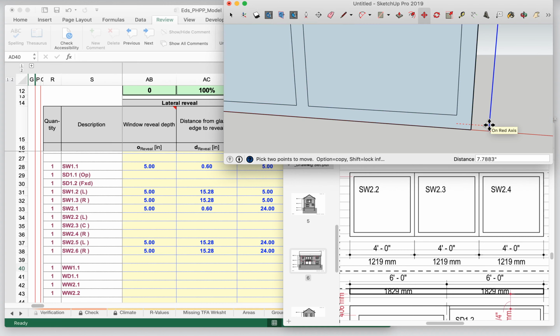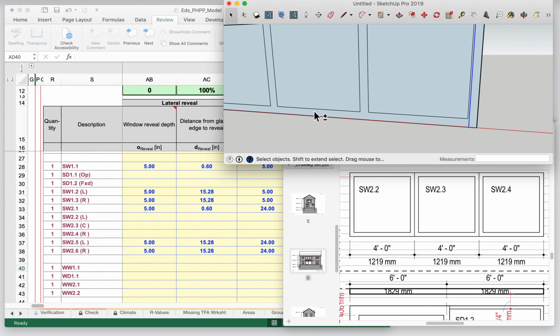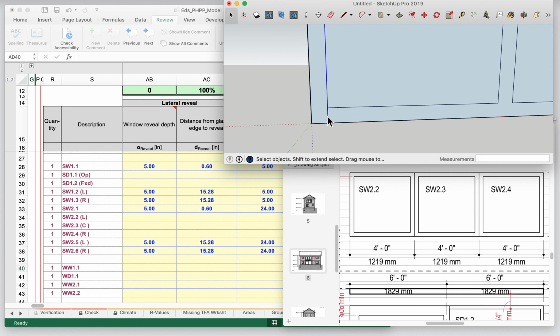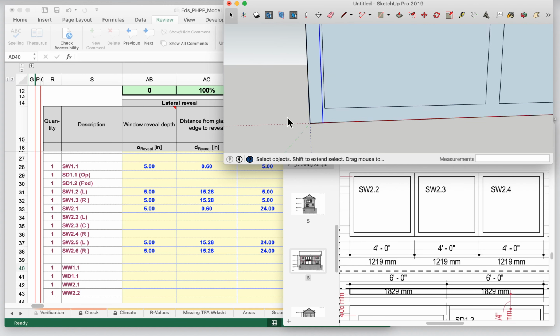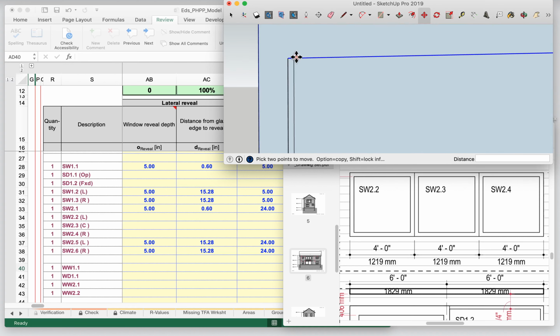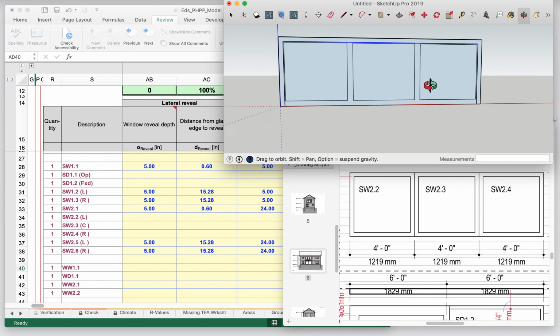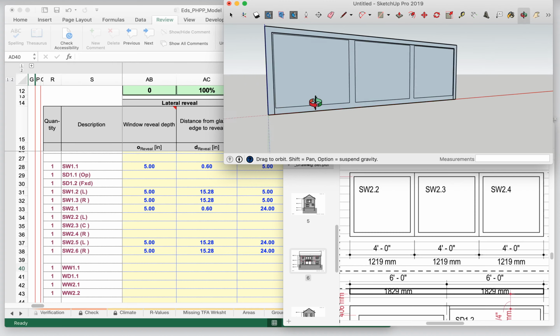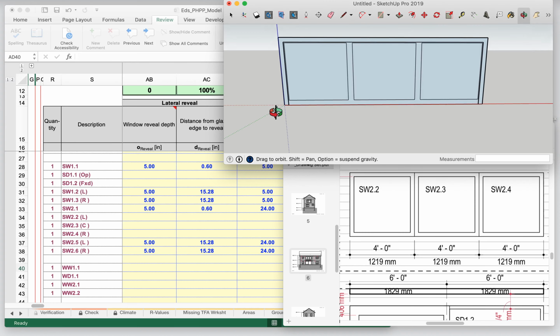It is in fact 15 millimeters or 0.6 inches off the face of our glass there. So I'll pull these over 15 millimeters. I'm just typing in that dimension there so that it's all dimensionally accurate, and then we do the same thing on the top, although again we already know the number there. Okay, so there is our situation. So that's kind of a different one to be sure.